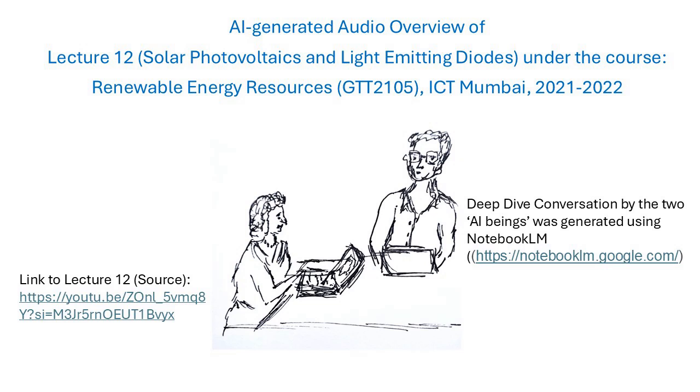Okay, series for voltage. What about more current, more power? For more current, you connect multiple panels or strings of cells in parallel. All the positives together, all the negatives together. That adds up the current capacity. Series for volts, parallel for amps. Got it. Good.